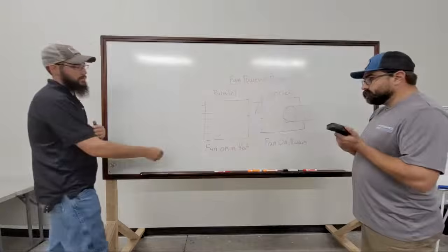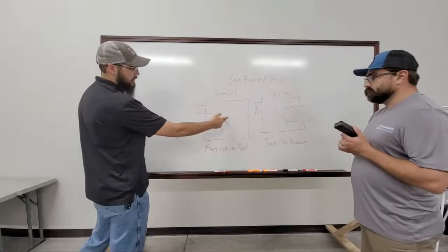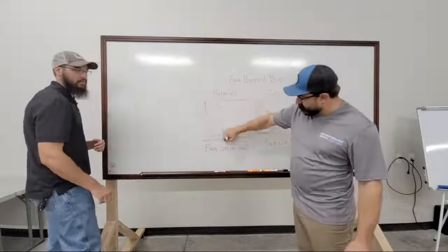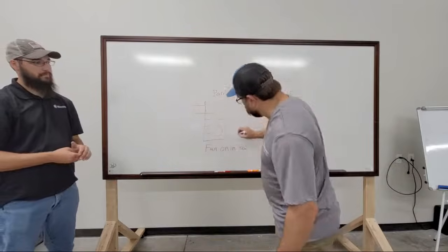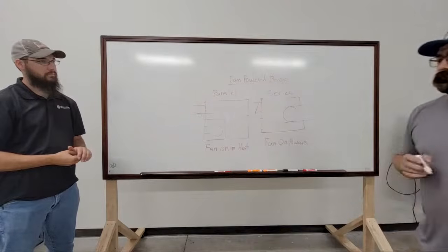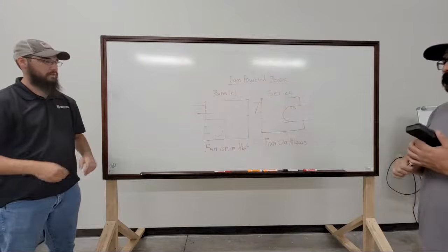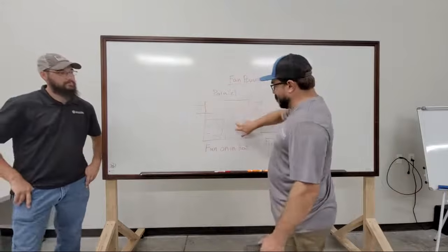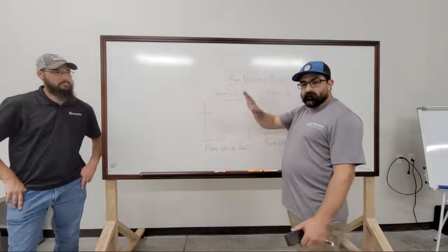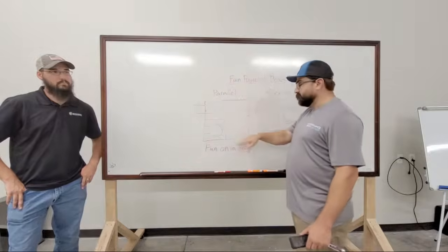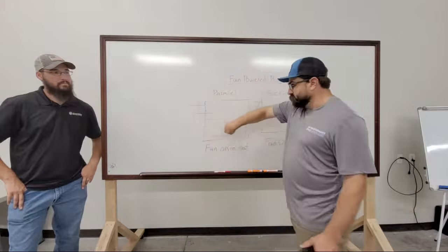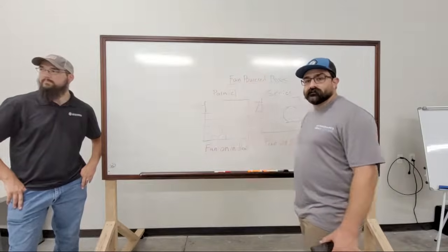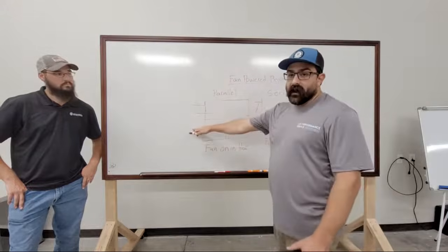The only other note I would add to that is on a parallel, you'll also have a divider here. Yes, usually there is a backdraft, backflow damper. Not always, but most. There's some that don't. What does that do? When this pressurizes this cabinet, this is just a barometric damper, so it's just hanging. It just flops in the wind. When the fan kicks on, the pressure pushes it that way and it opens. When the pressure comes from this way, it closes and seals. It's to keep it from flowing out the back.